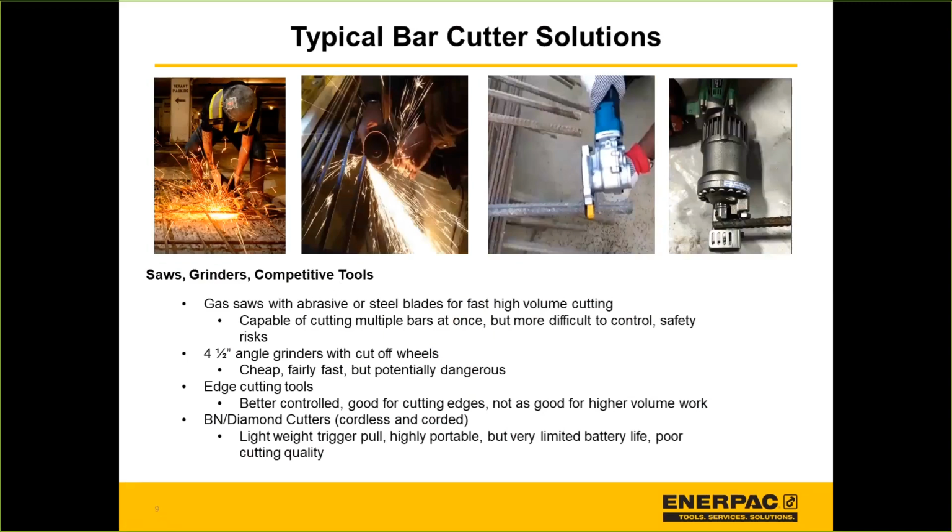So they do get the job done. We see them used more often on job sites than in fabrication shops. And part of the reason, I think, is that as much as the edge cutter brings advantages in terms of safety, it's not the fastest tool. So it's going to take the user a while to get through that rebar, say 5-6 seconds.